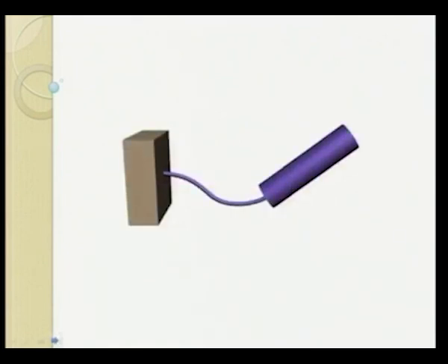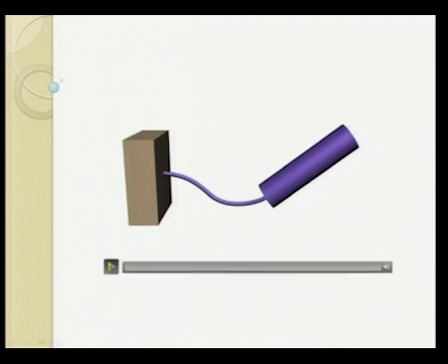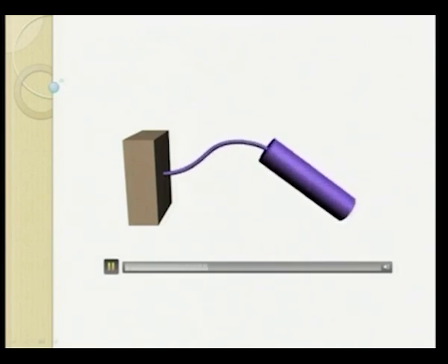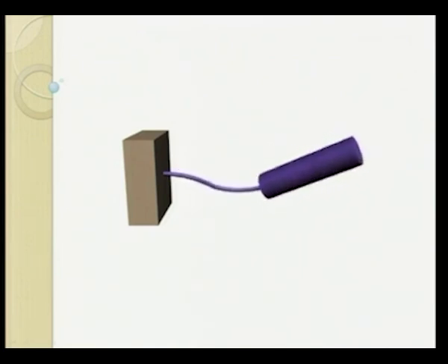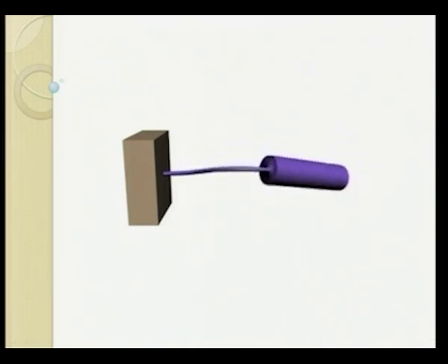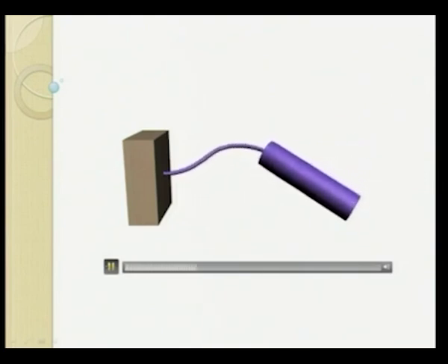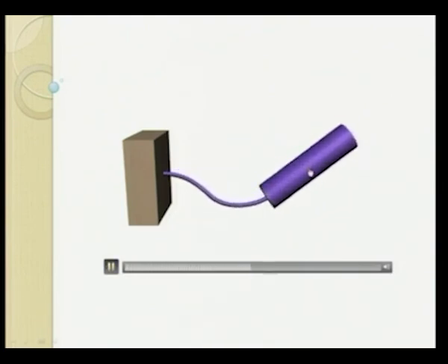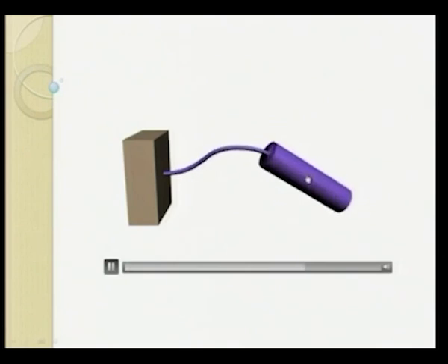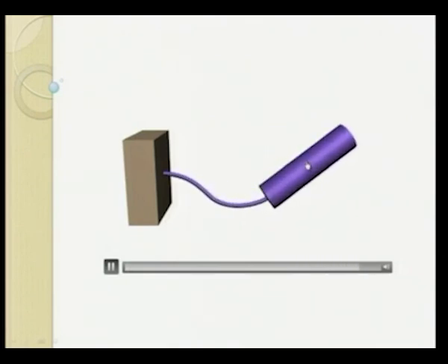This is the animation for the long rotor, in which whirling in the forward whirl direction is taking place. In fact, when we have synchronous whirl, the shaft bends in a particular configuration and remains in that position, and the whirl takes place. So you can see this is a pure rotation of the shaft, because we assumed the disc has tilting about its center of gravity.